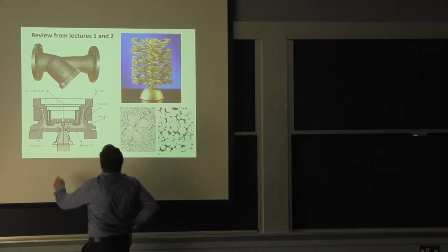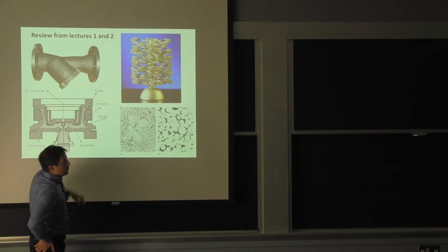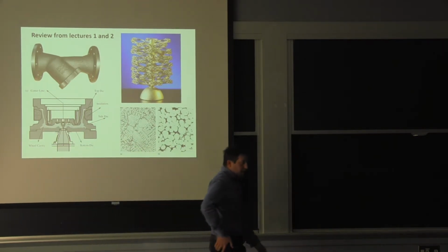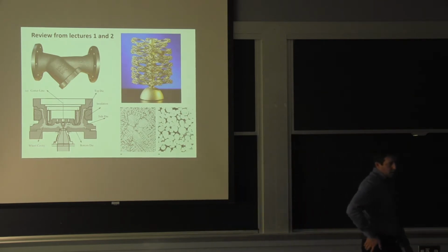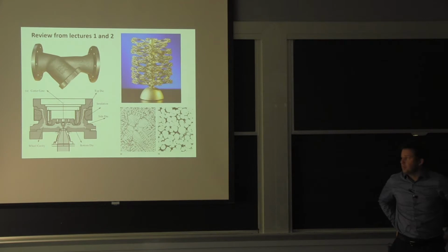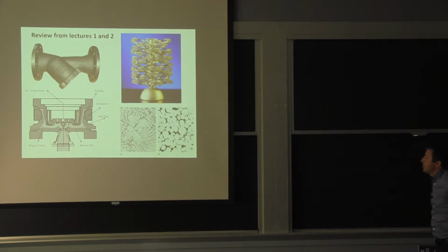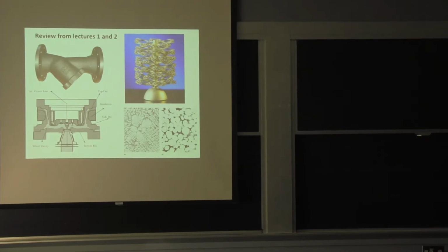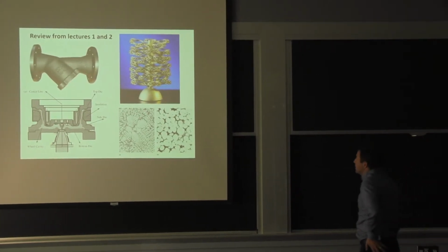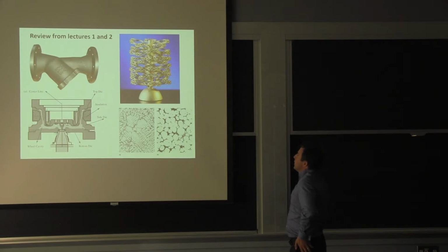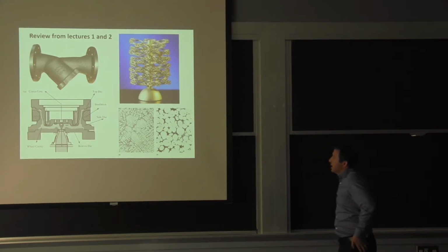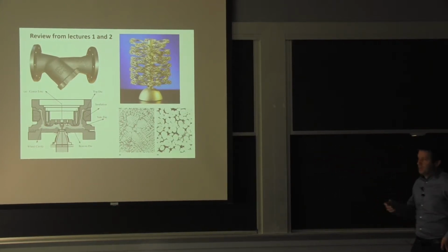But there are a lot of pipes and fittings and valves, like the one I'm showing here, that are used as cast. They come out of the mold, and then you machine just the surfaces where you have to make mechanical connections. We've talked about some of the detail process. You have a wax pattern on the upper right-hand side, where essentially you can make any shape you want and put it in a slurry to make your casting mold. When you're done with that, you melt the wax, and you have a hollow cavity to cast the different parts that you're looking for.